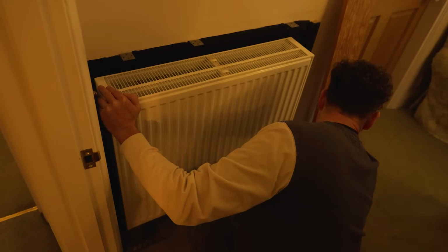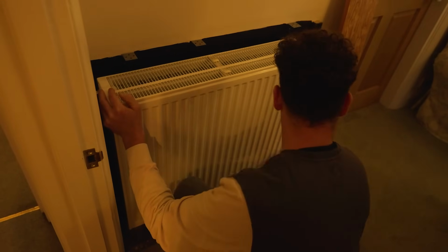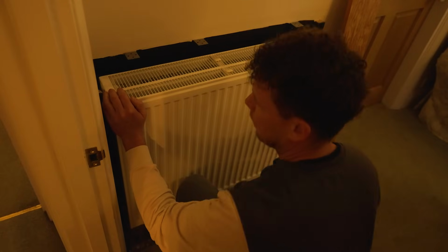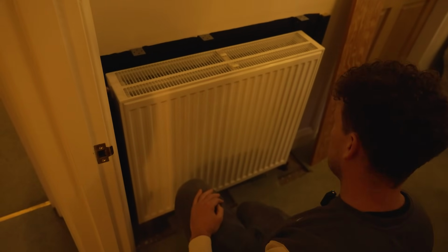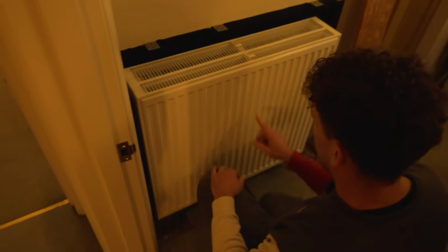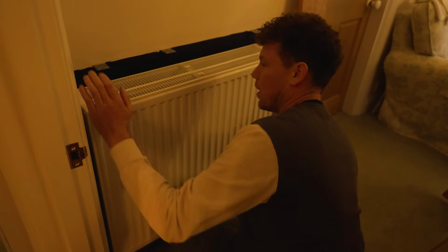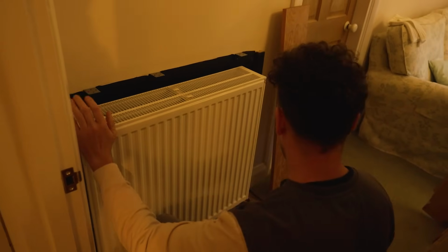This is nice and warm up here, it's nice and cold there, so you get a nice delta across it. Actually, I don't think there's quite enough flow to this radiator, to be honest. There's too much delta between the flow and return. But that is a more efficient way to install a radiator. It's never been very efficient, this radiator. This hasn't got enough flow. We should have a delta T, so flow temperature difference between here and here of 5 degrees. This is room temperature. I'd say your delta T across there is like 15 or something like that.